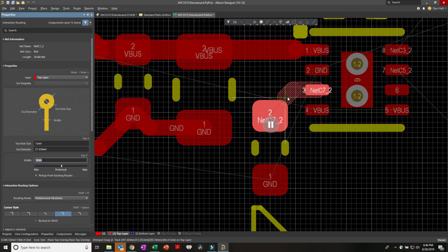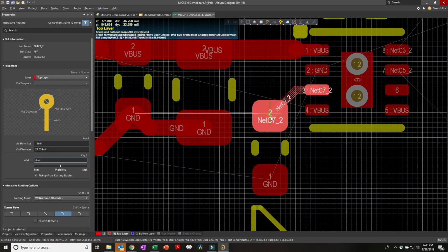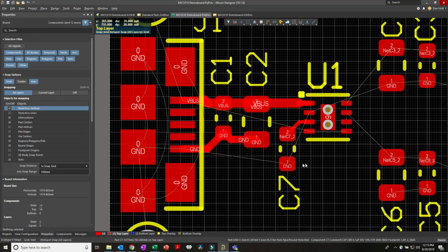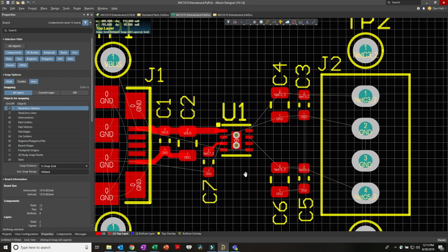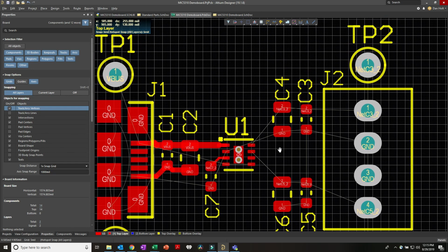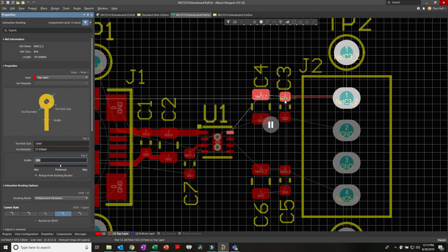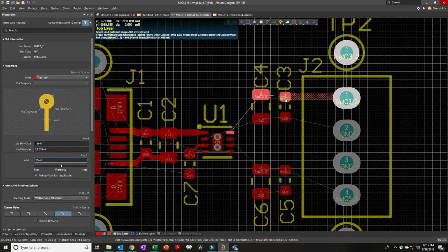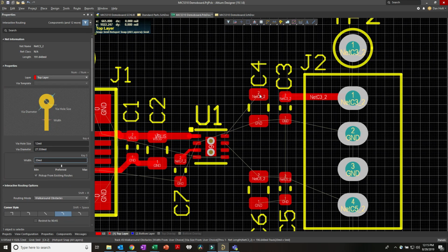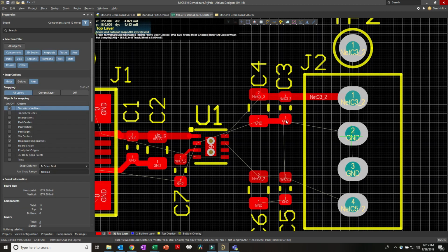This could be something really small, like an 8 mil trace. It's just a signal. Okay. Let's keep going on the routing here. Again, I tend to start doing everything on topside routing, so I tab 20 mils.